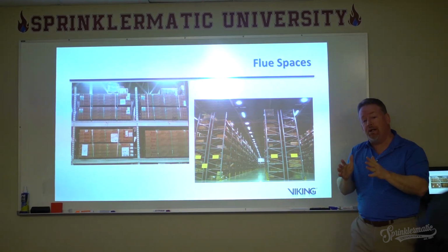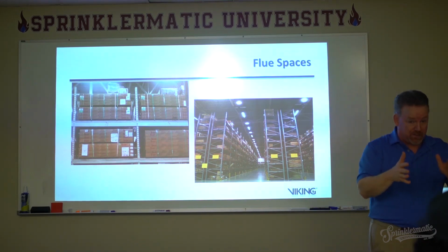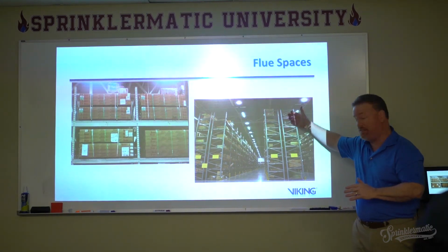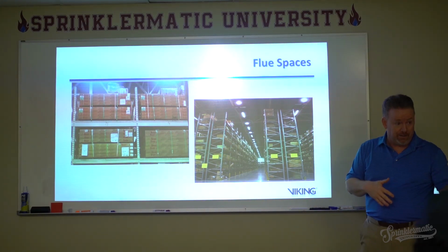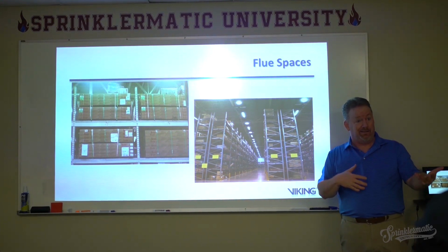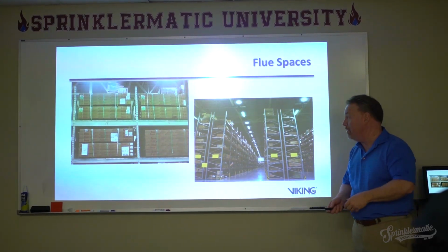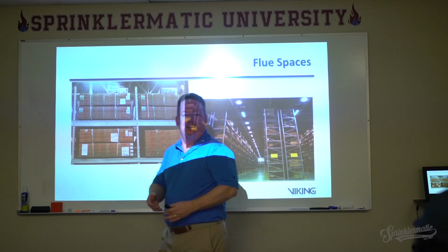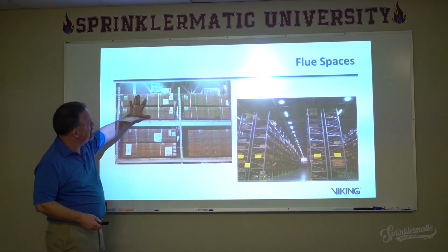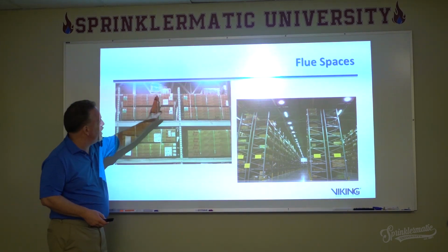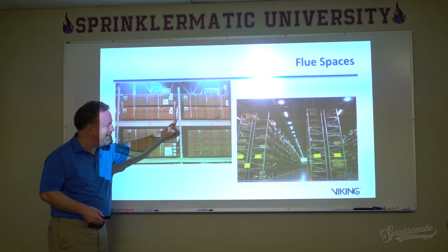Okay, so flue spaces become a critical component not only to the design, where the designer is assuming flue spaces are going to be maintained, but also to the inspection, to the inspector coming around, making sure that flue spaces are being maintained. Because remember also, let's just say I've got a couple of smaller loads in here, but I can only put two loads in here because I need to maintain my flue space.